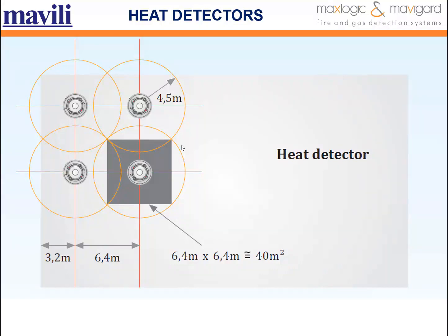Let's talk about heat detectors. Generally, heat detectors are accepted to be less sensitive than existing detector forms. Heat detectors with rise rate algorithm are more suitable where ambient temperatures are low or only change slowly. Fixed temperature detectors are more suitable where ambient temperature can fluctuate quickly in a short time. Heat detectors can resist adverse environmental conditions more than other fire detectors.